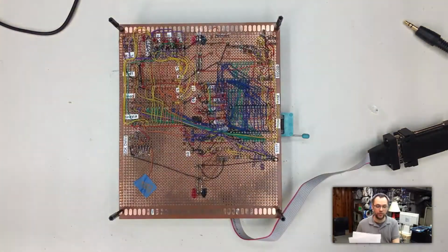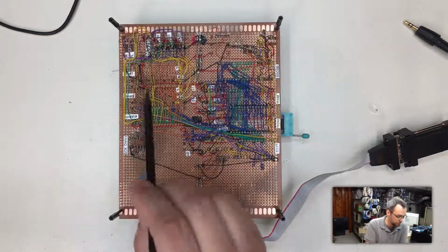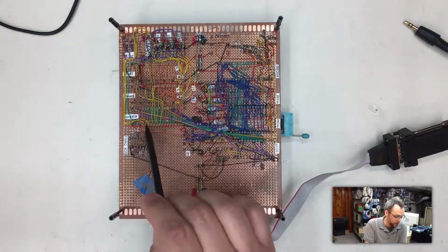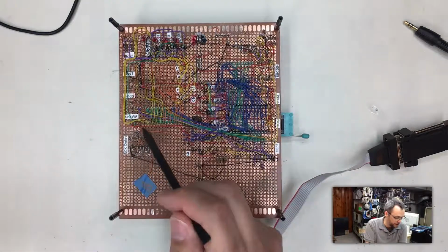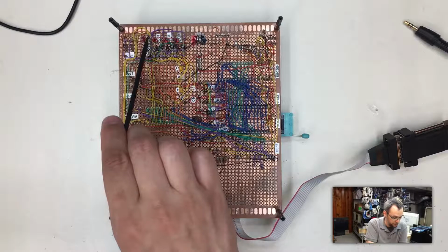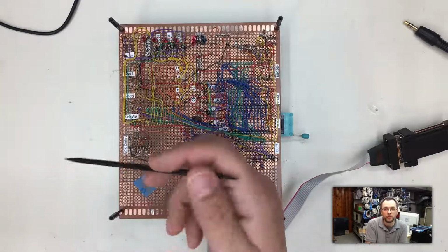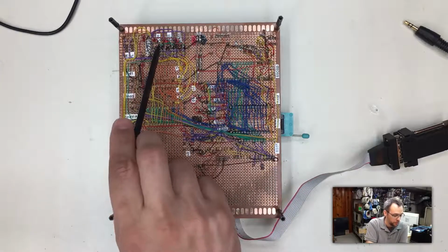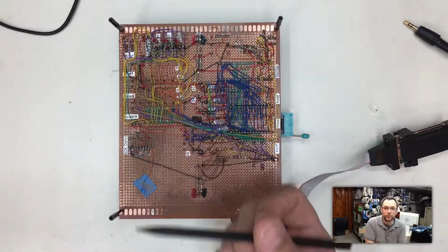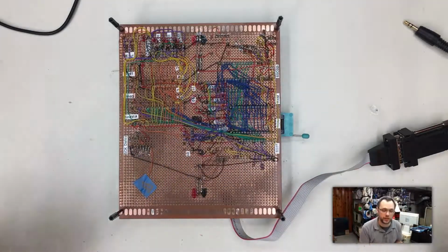I want to make sure that by default, when you turn the computer on, a 1 value is implied instead. So these come up into this inverter, which I talked about before, and it flips them over to 1s, to a positive value to go into these. So on boot, basically, the chips are all inhibited.